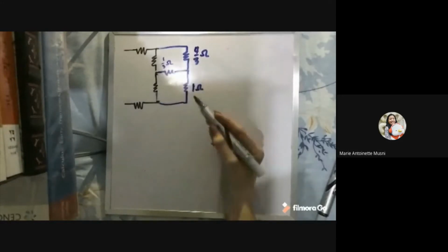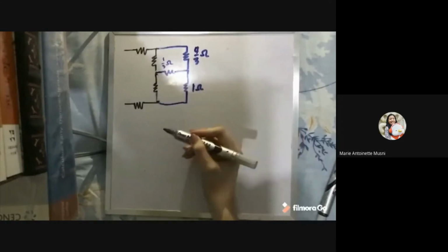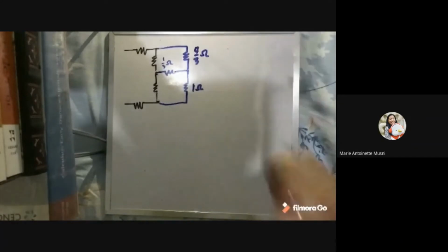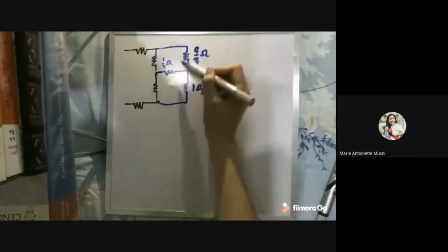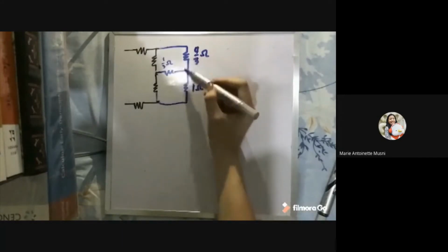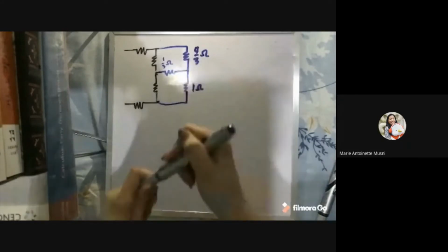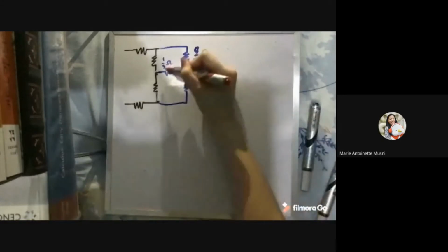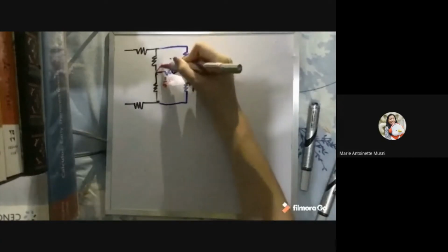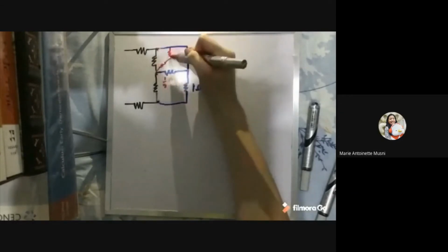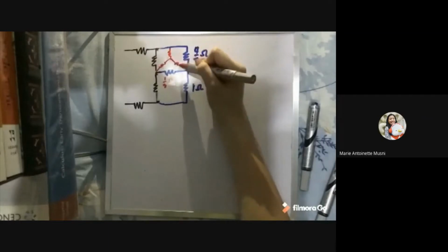Now, again, we don't have any obvious series and parallel connections, so let's move on to our transformation. You can see that this is a pi connection, so we can make a new Y connection here. Let's move this 1/3 ohm there, and redraw the circuit for a Y connection here.